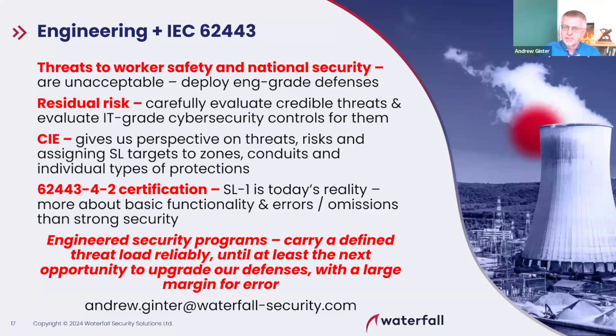Don't get me wrong. There's a role for next-gen firewalls. You have firewalls inside the OT network, typically dozens of them. You have firewalls on the IT network, typically another dozen of them. You put one gateway in place at the criticality boundary between the network with business consequences and the network with unacceptable physical consequences. That's where the gateway goes. The gateway is unidirectional. The gateway is also different from a firewall in that firewalls are routers.